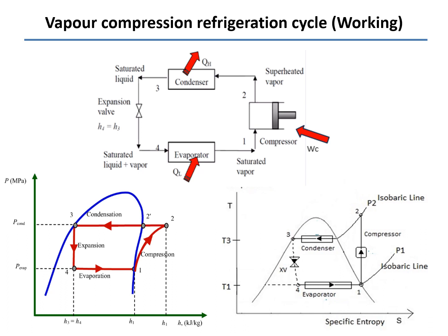Now, in this slide, I am talking about the working of the vapor compression refrigeration cycle so that we can understand how the domestic refrigerator works. Here you see the schematic or block diagram: compressor, condenser, expansion valve, and the evaporator. To understand the thermodynamic cycle, we require some property diagrams. The first is the pressure-enthalpy diagram, known as the pH diagram. The second property diagram, which we also use for analysis, is the temperature-entropy diagram, the TS diagram.